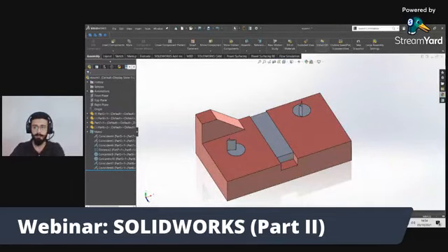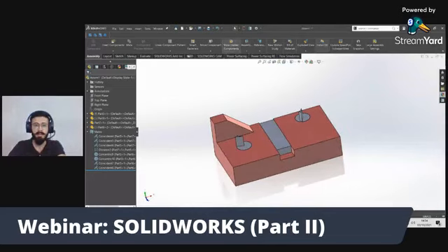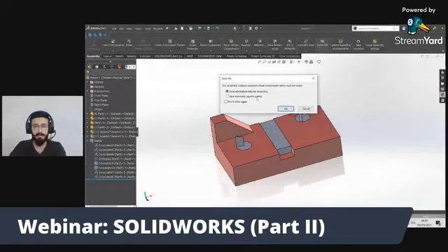And this is the part of our assembly. Now I will be showing some more things in our assembly. You can add one more assembly in another assembly. If I save this, let's add some from my storage. Insert a new assembly. See, there are options: insert a new assembly. Oh, I have to save this one. Save all. The desktop. Save externally inside the assembly.